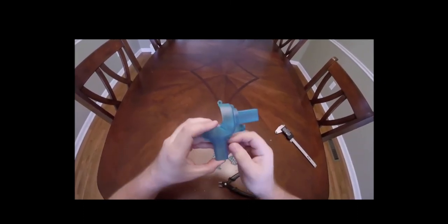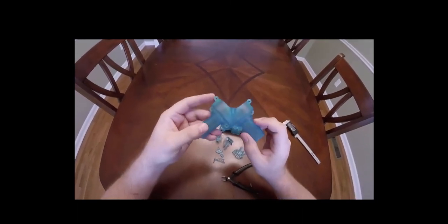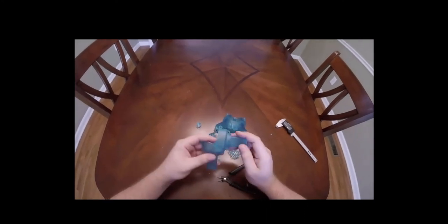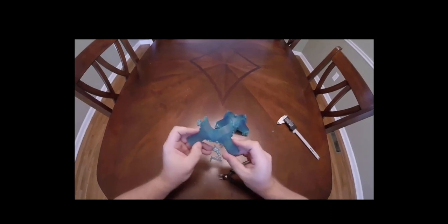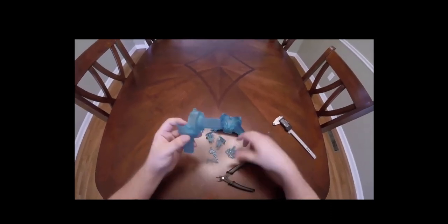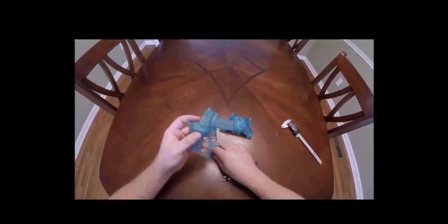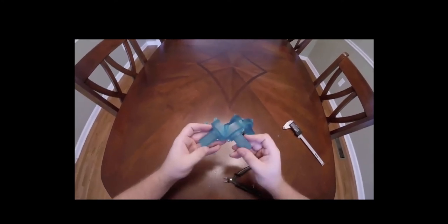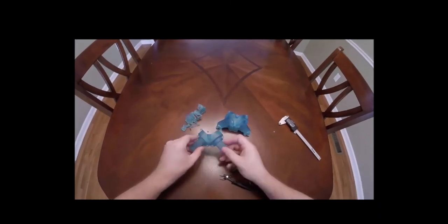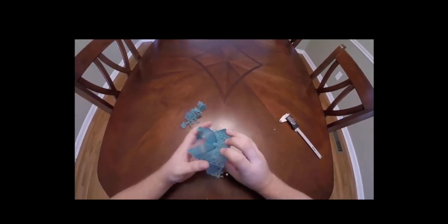Like any manufacturing process, you can go back and do any secondary post-processing steps you might want to do, like sanding, which is definitely an option for a part like this. But overall, you can see when you fine-tune your support structures, I think I used 0.55 millimeter supports on this part at a 0.9 density. As long as you're not way over supported, the supports come off the parts really easily. Same thing will happen with this part.